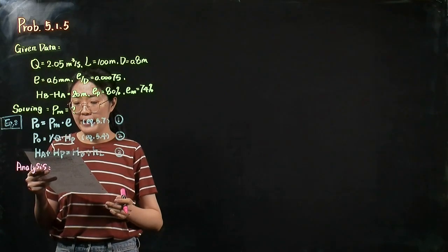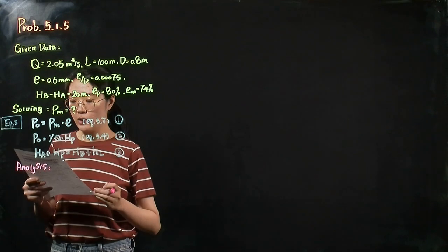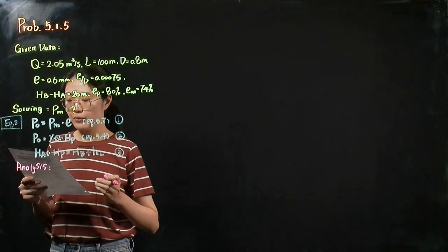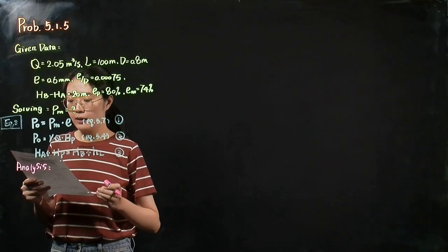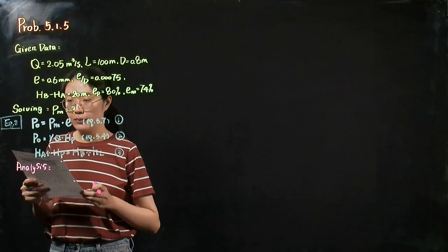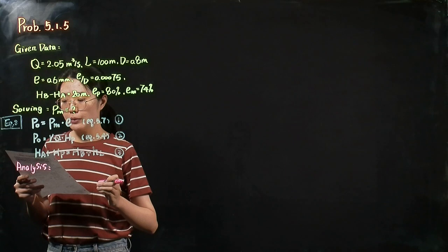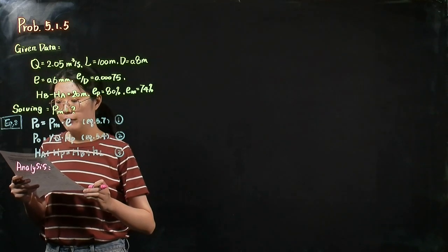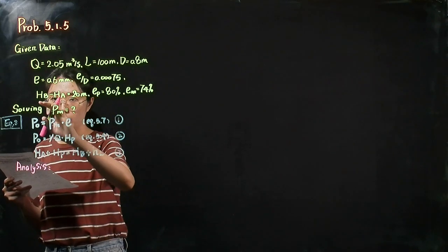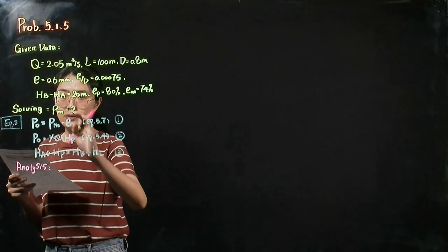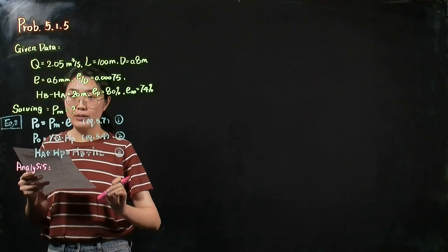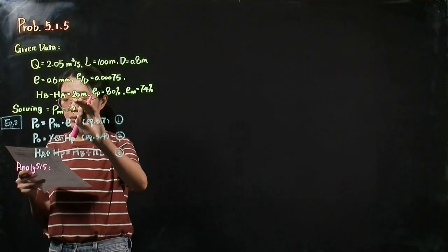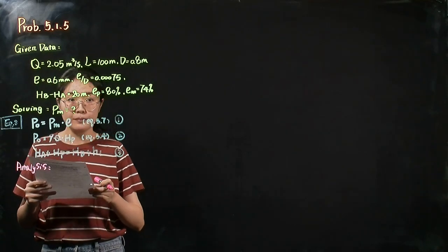It also told us the water surface of reservoir B is 20 meters higher than the water surface of reservoir A. And because we assume the velocity and the relative pressure at the water surface equal 0, in other words, the total energy of the surface point in reservoir B minus the total energy of the surface point in reservoir A equals 20 meters.